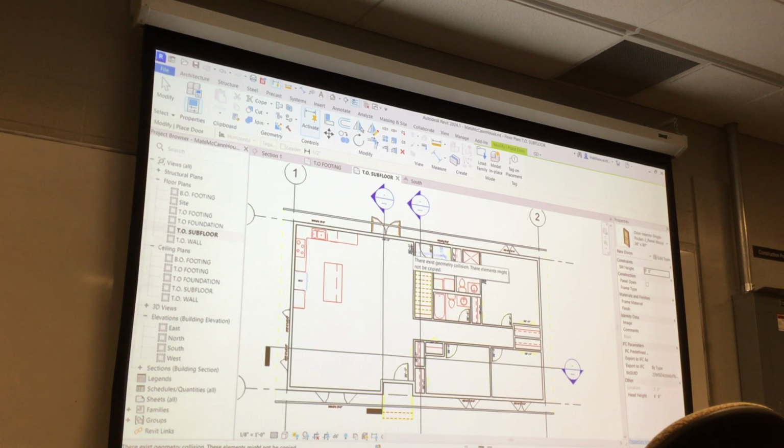Okay, I've got this set up to put the roof on, that's why my view range is set to show you something else, and I don't wanna change it right now. And same thing right here, like a lot of you decide, well, I'll put a pocket door here, because there's no bifolds or whatever, and a bypass doesn't give you as much room, but you can't have the pocket coming out into the hall, right? You gotta have room for it, okay, so think about that a little bit. A lot of you spent a whole bunch of time putting beds in and all that kinda stuff, because it's fun, but some of the other stuff wasn't there, okay?